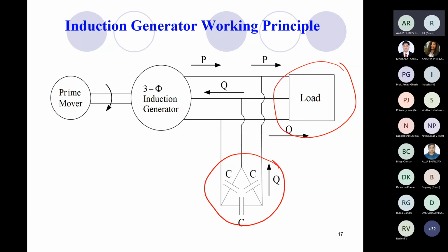So when the rotor of this induction generator rotates with the help of this prime mover, it will generate electricity using the field which was already there due to residual magnetism. When a small voltage is generated, that will supply some current to this capacitor, and this capacitor will charge. Therefore this capacitor now will produce some current, and that current will further increase the strength of the magnetic field, thereby producing more voltage. In this way the voltage build-up procedure will initiate.